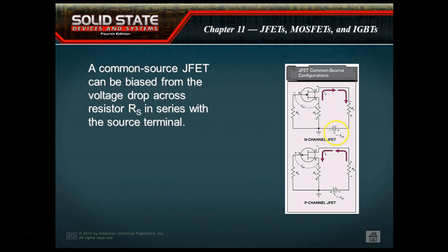the way you would see this on a schematic, is we'd have a power source up here at the top, of course, and that would be here. This would be our drain resistor, and it would come through to the FET or the JFET, and of course this is an N-channel JFET. Here's our source resistor, and then this would be our gate resistor. Now, of course, here they're just drawing the bias of the thing. So this is the way we would draw it. This is the way our schematic would look.